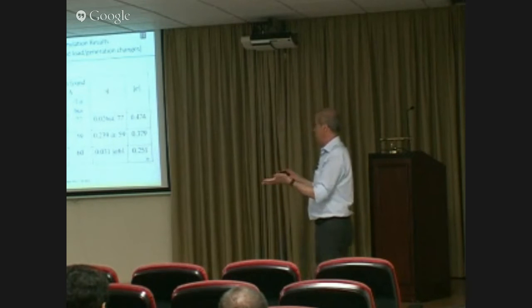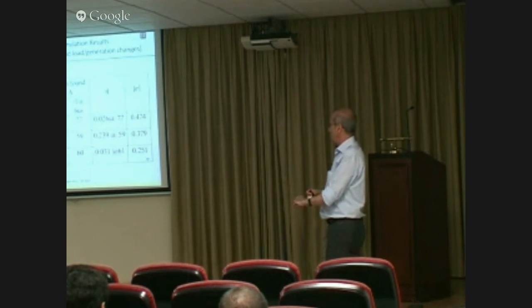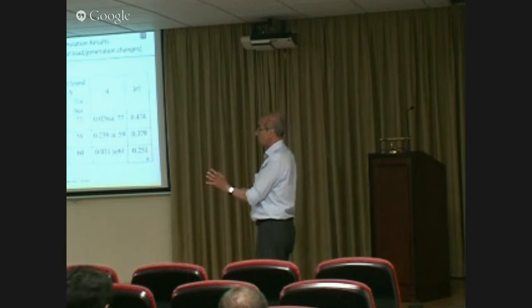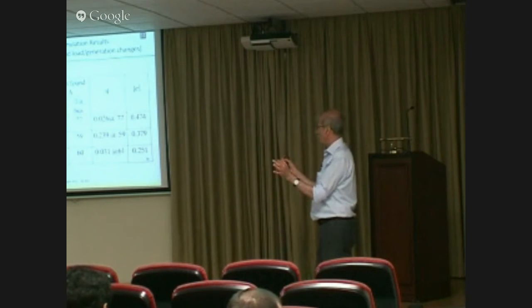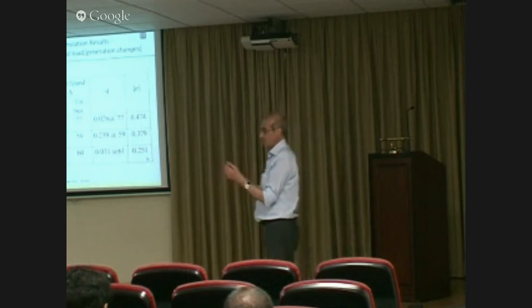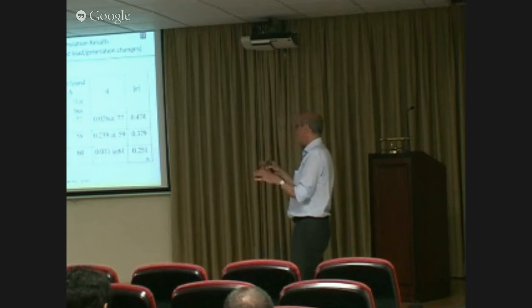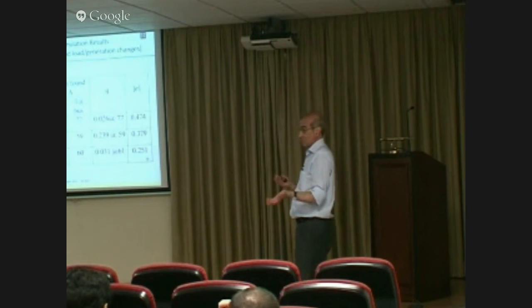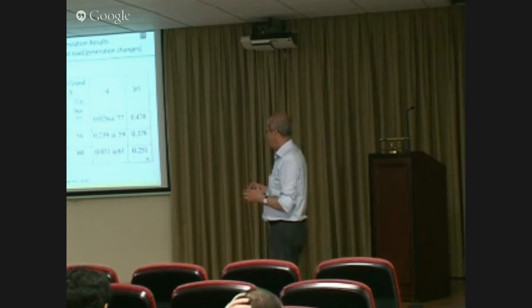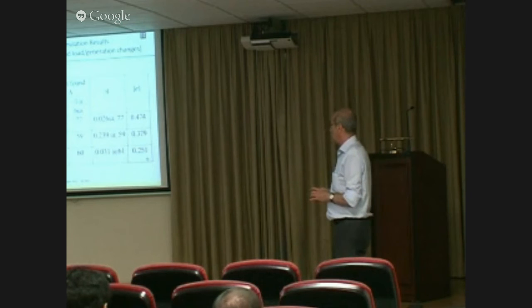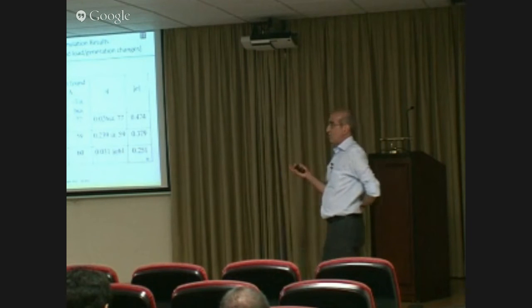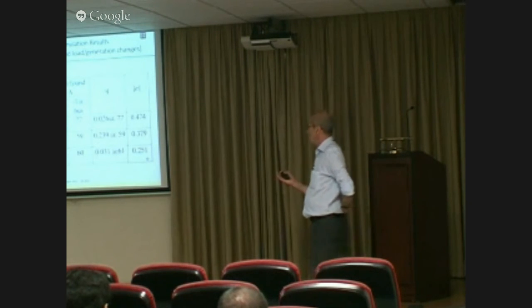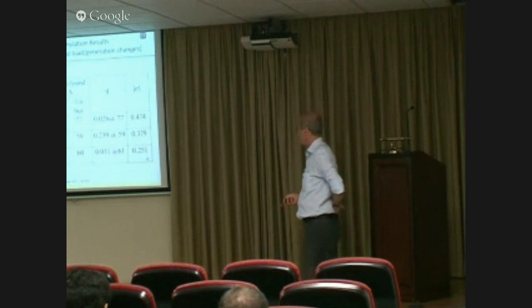So that means it immediately shows you the limitation of the technique, which means if you have a very lightly loaded line and the line is taken out, since the light load may be in the same order as this load change, slow load change, you may not be able to differentiate whether it's actually a load change or a line outage. So there is that limitation for the lightly loaded lines. But then again, you might say, okay, if lightly loaded line is taken out, maybe it has a small impact on the contingency analysis, which is why you need the external network equivalent, so forth.